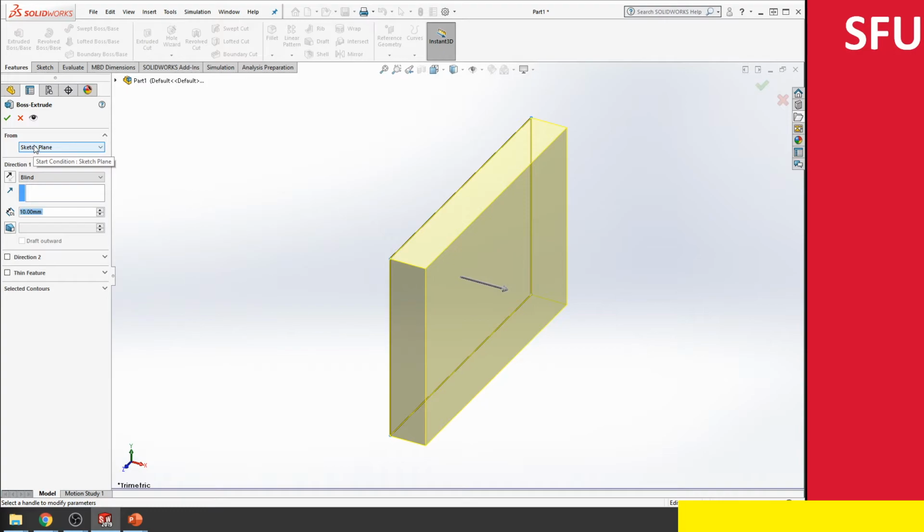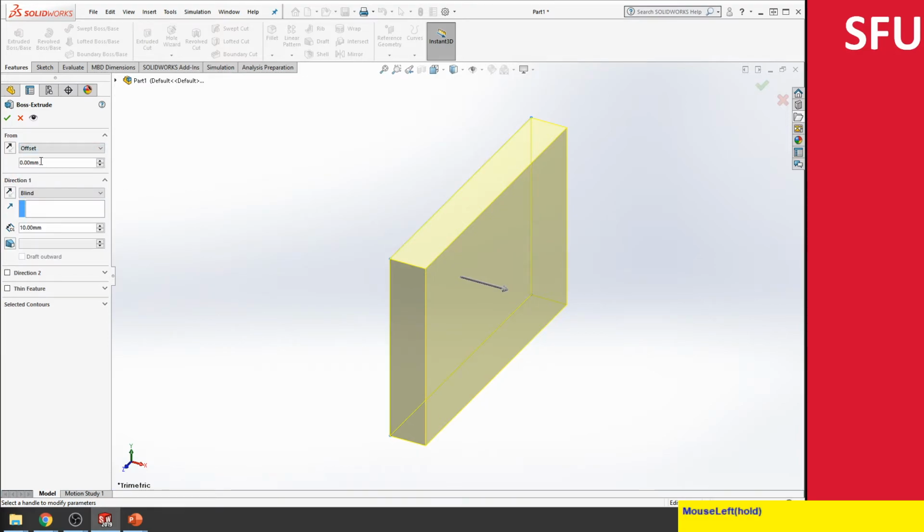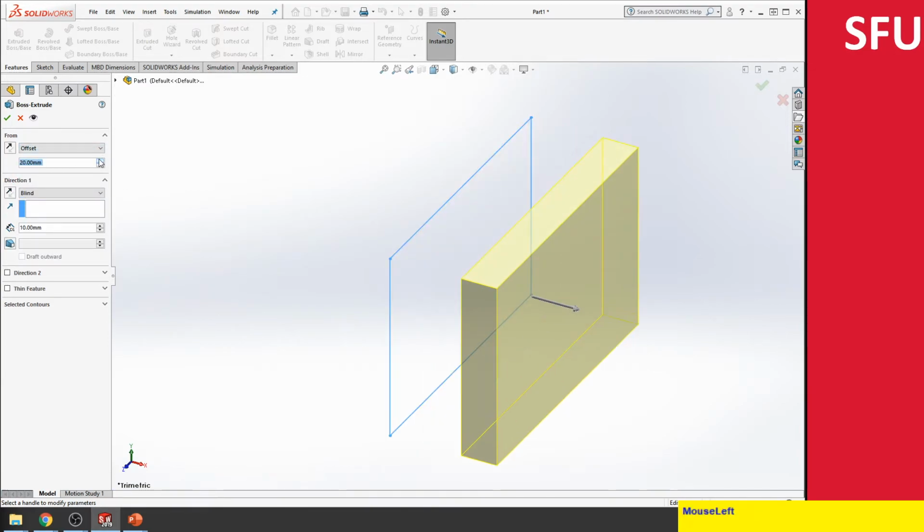The first option is From, which tells me from which point the extrusion begins. Instead of starting from the sketch plane, I can select any of the other planes. If I had another plane parallel to the sketching plane, I can start from that particular plane. I can similarly start from a vertex, but since we don't have any other reference surface, we're going to click offset and then randomly increase this.